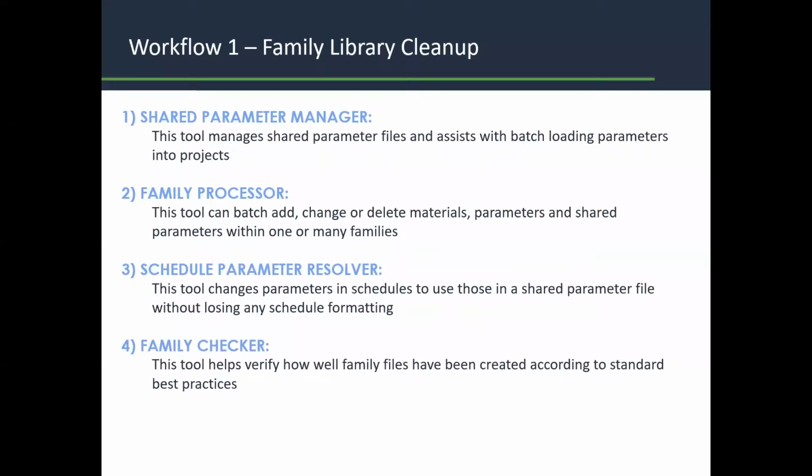Okay, so first we'll take a look at the family library cleanup, which, as we all know, is the primary source of BIM standards within a firm. The first tool we'll take a look at is the Shared Parameter Manager. This tool manages shared parameter files and assists with batch loading parameters into projects. So we believe it is best practice to have one shared parameter file for the entire firm. Not one per office or one per team, but one shared parameter file. And Shared Parameter Manager allows us to achieve this.